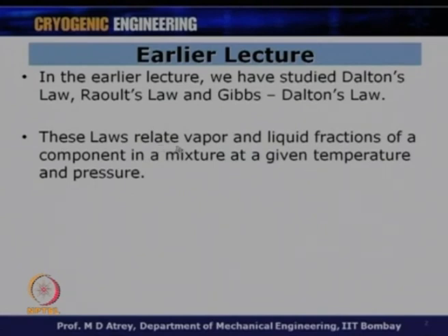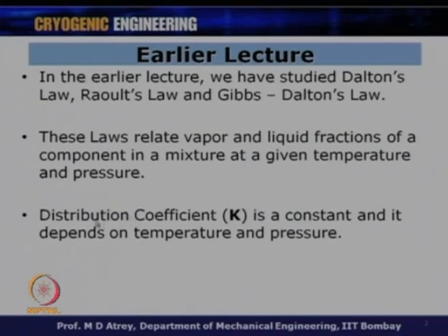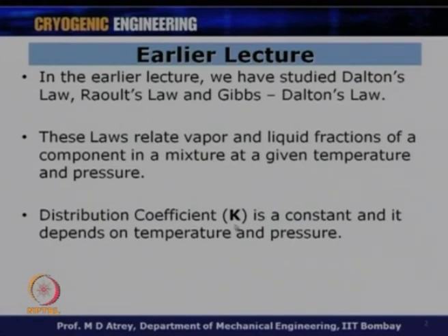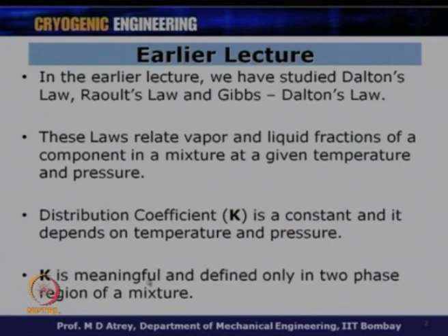These laws relate the vapor and liquid fraction, the y and the x fraction of a component in a mixture, at a given temperature and pressure. We also studied the concept of distribution coefficient, which is K, and we found that it is a constant and it depends on the temperature and pressure of a mixture. So, what is the temperature of a mixture? What is the pressure of a mixture? According to which one can find out the distribution coefficient, which is nothing but y by x, or a molar fraction divided by the corresponding liquid fraction in a mixture, and this gives a value of the distribution coefficient. The K is normally given in a two-phase region.